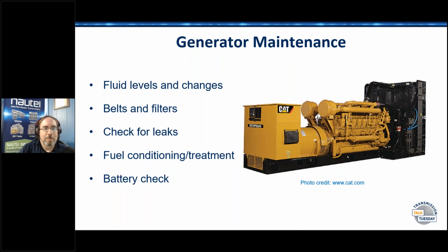Oh gosh, yeah. Good morning, Jeff, and everybody on. With the storms that we get out here on the plains, you've got to think of those little things. One of the first things I did with the generator that we put in at one of our sites was to make sure that the front of the radiator was well protected from hail. Manufacturers like Onan or Kohler will have protection for the radiator, but the spacing is so wide that even small hail with a little wind behind it will damage your radiator fins pretty badly. So hardware cloth is good.